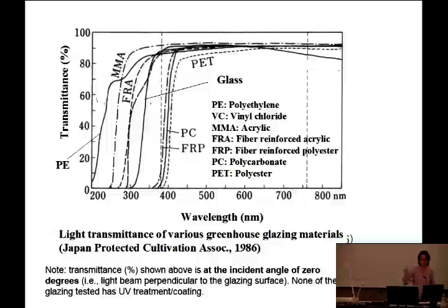for greenhouses. Transmission percentage over the spectrum starting from 200 nanometers, which doesn't exist in nature. So you want to focus from 300 all the way to higher or longer radiation. But anyway, I have glass in here. Okay, glass. So every single one has pretty much good transmission between 400 to 700. It's pretty much 90%. This is a perpendicular lab measurement, okay?